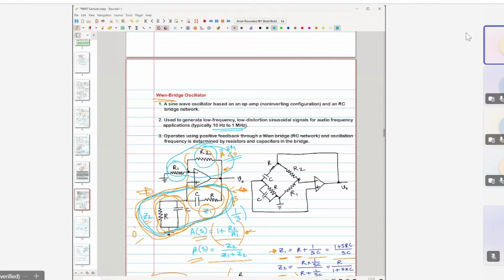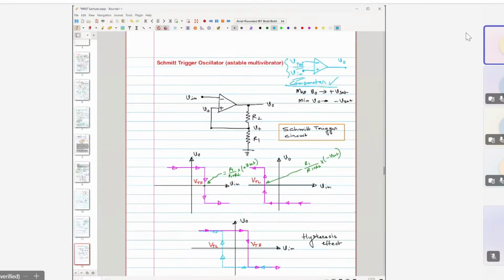I hope all of you are quite familiar with the op-amp comparator. So the op-amp has two terminals, an inverting terminal and a non-inverting terminal. Suppose the non-inverting terminal is connected to the input voltage, and with the inverting terminal we use a reference voltage source, V reference, and this is the output. Then there is no feedback from the output to the input, no negative feedback. Then what will be the relation between V output, V reference and V input?